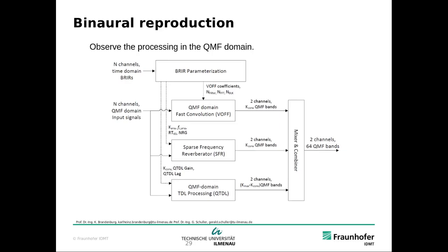But QMF, we saw, has very high attenuation starting at the subband after the neighboring subband. So you have much better attenuation of alias components in this way. And this is important in this application. And that's why QMF filter banks are used, or rather PQMF.